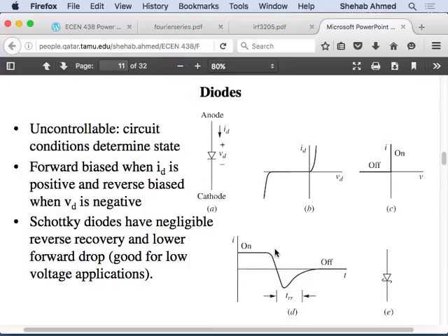Yes, sir. So that happens naturally? Yeah, it happens naturally, because if you remember your 325, they had three pictures. They had when the PN junction had no voltage across it, a PN junction with a voltage polarity in one direction so that the device is forward biased, and then one where the voltage polarity is such that the device is reverse biased, and they had the depletion layer thick on one side, thin, and then an average value where the barrier voltage was 0.7 volts, right?